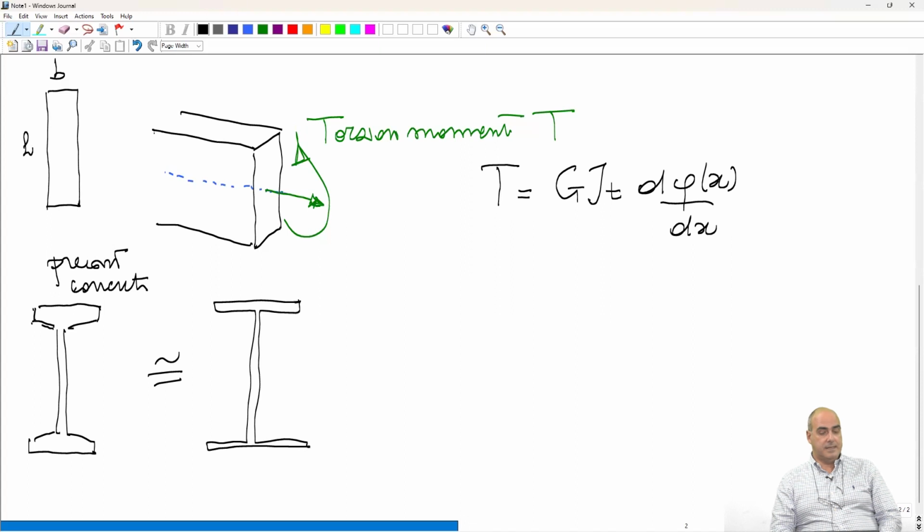Well, the difference is that the rectangular cross-section beam is, I will say, not a wise structural element. Because you have the beam, simply supported, gravity load, the maximum bending moment is only one cross-section.